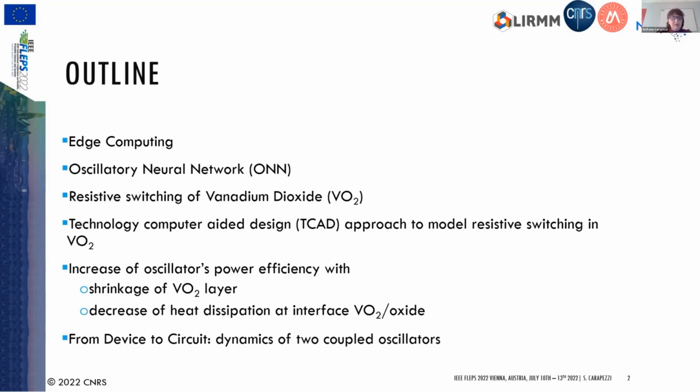I will show how I have used this approach in order to investigate some issues related to some features of the device, like for instance, how to increase the power efficiency of the oscillator. And also, through a linked technique called TCAD mixed mode, it is possible to scale from the device to the circuit, and so to have also an assessment of the dynamics of the circuit, which is quite important because neuromorphic computing is an analog computing approach, which means that it's the physical dynamic of the circuit which yields the output of the computation.